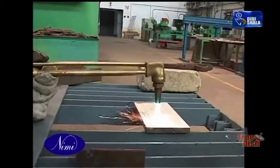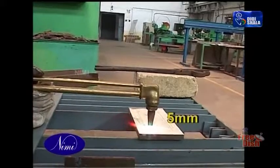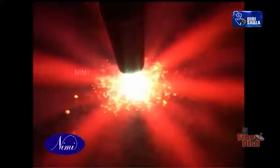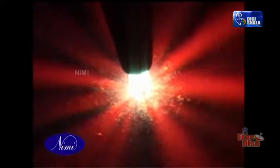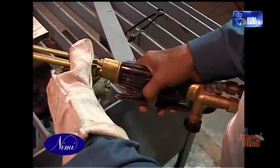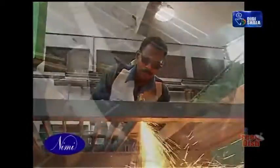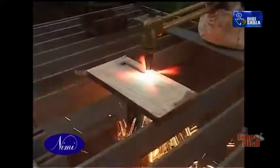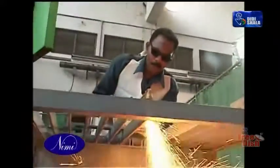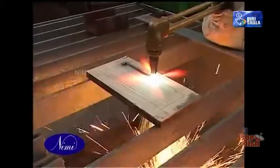Hold the torch with the inner cones of the preheating flames 5 mm above the end of the line to be cut. Hold the torch in this position until the spot becomes bright red. Open the cutting oxygen valve slowly and steadily by pressing down the cutting valve lever. If it is started correctly, a shower of sparks will fall on the opposite side of the work, indicating that the flame has pierced the metal.